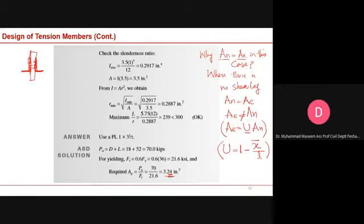This part of the angle will be in the fully stressed condition, and this part of the angle will not be in the fully stressed condition. There will be a lag in the stresses that are developed in this member. When you have this type of scenario, we call it shear lag.